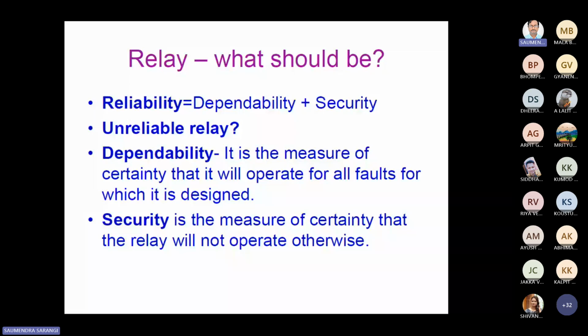In those cases, we'll say the relay is losing the security. मतलब relay जो है secured नहीं है. जैसे आप लोग MCCB या फिर MCB अपने घर में लगाए होंगे, तो MCB जो आप लोग अपने घर में देखते हैं, what happens if you put a 1 kilowatt iron or 1 kilowatt heater in a 5 ampere plug? Suddenly the MCB will go down. You cannot do your work, right? So the work is not secure.